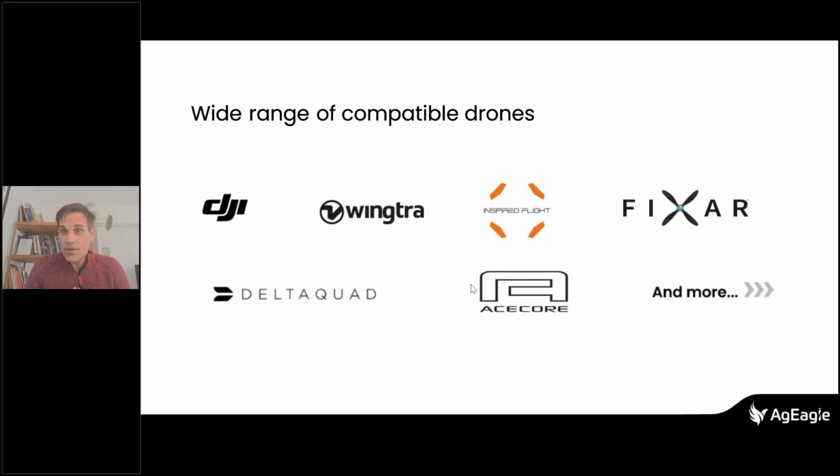The second thing that needs to be taken into account is when do you fly, right? The panel should come in second place on the quality of the data. The first parameter that you need to check is how is the day, right? For best results, it needs to be a clear sky, or even better, a 100% cloudy sky, so there are also not any shadows. Then use the calibration panel under these circumstances. That's the best quality data you can get.